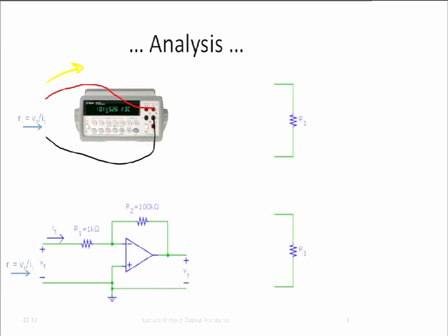Ideally, what would that current be? Zero, right? When we make a measurement, you don't want to disturb our circuit at all. You don't want a new current to start flowing that didn't flow before. But of course, we know that maybe we can approximate that ideal solution, but not quite. It turns out voltmeters, the electronic ones, typically have internal impedances of 10 megohm. Okay?